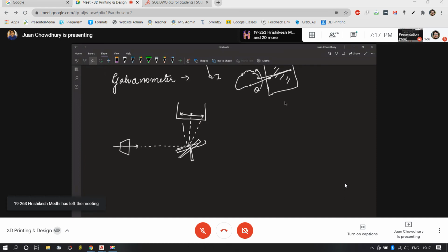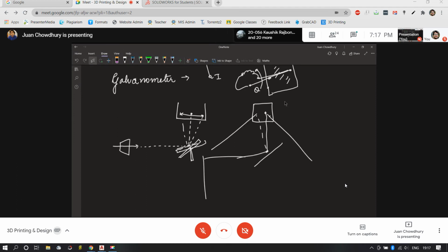If I have a pair of these, two of them, each facing at 45 degrees, and another one facing, say, me, this one hits over here, this one hits over here. Now I can deflect this laser here, as well as the laser that is coming towards me. So if I have a resin in between, I can create the X as well as the Y motion. Motion of what? The laser. By this, can you think about the concept that I'm not moving the laser head? It is static. All I'm doing is moving the mirrors.